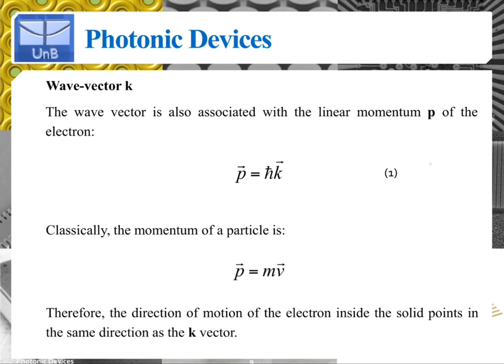Also recall that when we were talking about indirect bandgap semiconductors, we had a band structure like this, and in order for there to be emission, we needed the electron to make a downward transition from the conduction band into the valence band, and it would need to undergo a change in wave vector k of exactly the wave vector mismatch delta k, besides undergoing a change in energy.